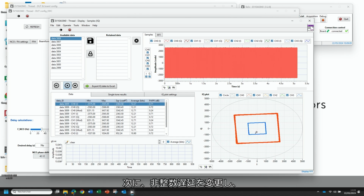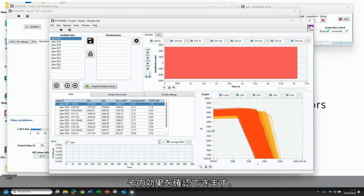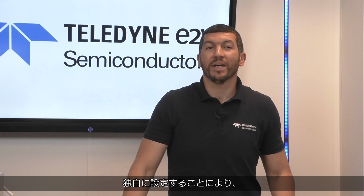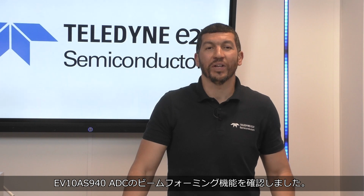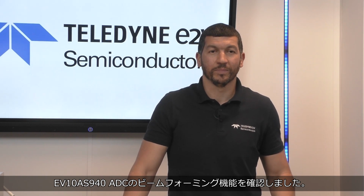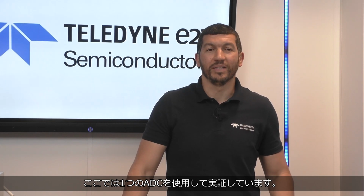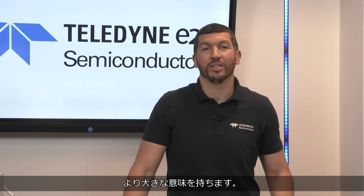Then we can modify a fractional delay and see the effect. The phase between the channel modified and the others have changed. In the second part, we have seen beamforming capabilities of the EV10AS940 ADC by configuring gain and delay setting for each digital channel independently. This capability of beamforming is demonstrated here with one ADC. Obviously, this capability makes even more sense in multi-chip applications.